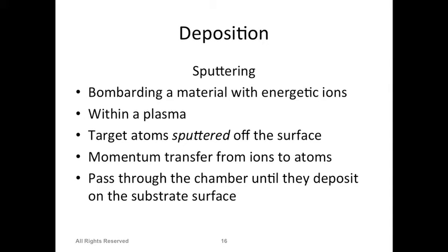So what about if we want to deposit alloys, like two materials, and you want to have a layer which has two different materials, let's say chrome and gold, or silicon, or copper and aluminum. Aluminum and copper were very commonly used previously as alloys, because aluminum has some electromigration problems, which we'll not discuss, but there are some issues that after a certain temperature it starts heating up, and then it starts breaking. The electrodes start breaking in different places.